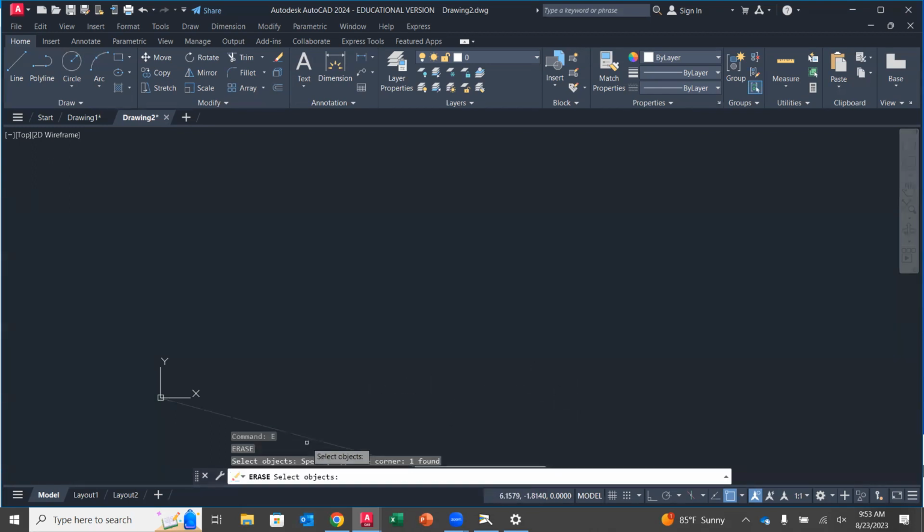Hold on. Let me try again. I think because I'm going back and forth, I have to activate my screen, and sometimes, so I'm going to do my 0, comma 0, enter. And then I'm just going to push this over to the right. My next point is going to be 5.5, comma 0, enter. There we go. Do you guys get a horizontal line that's 5.5 to the right of your 0, 0? That's what you should get. All right. Anybody need another demonstration of that, or you're good for right now?